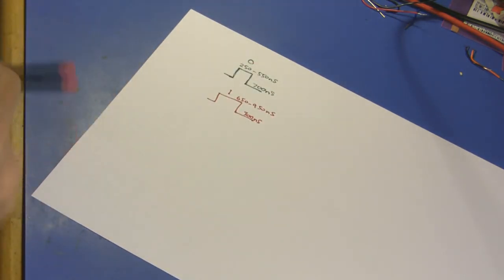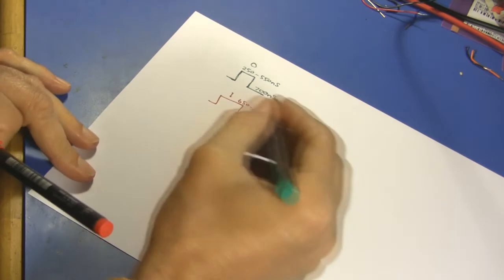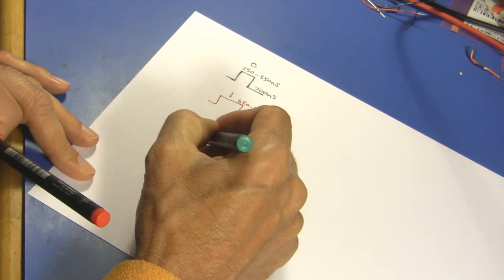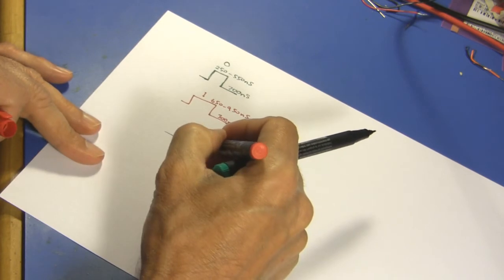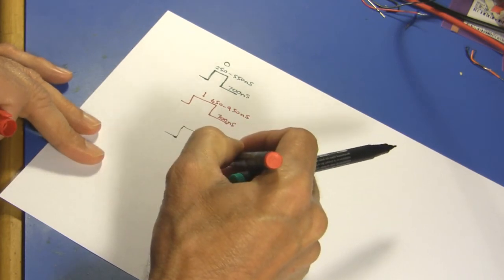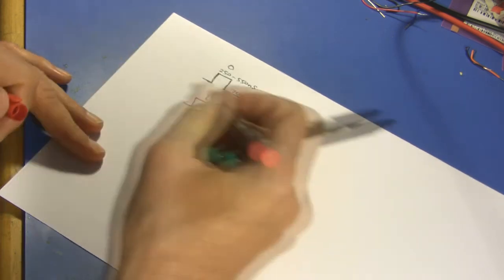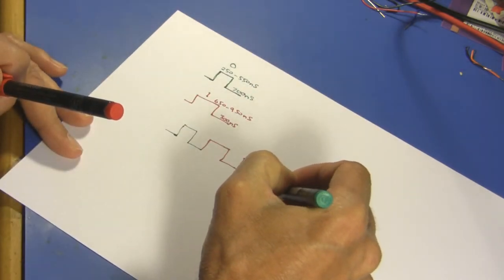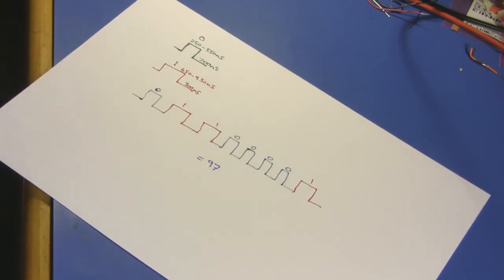So to send data, we just simply string these pulses together to make up the 8 bits that we actually want to send. So if we want to send starting with a 0, we send a short pulse, and then a 1, we follow it with a longer pulse, say another 1, another longer pulse, and then a 0, a shorter pulse, and we just keep going like that, stringing them together until we have our 8 bits for one LED like this.